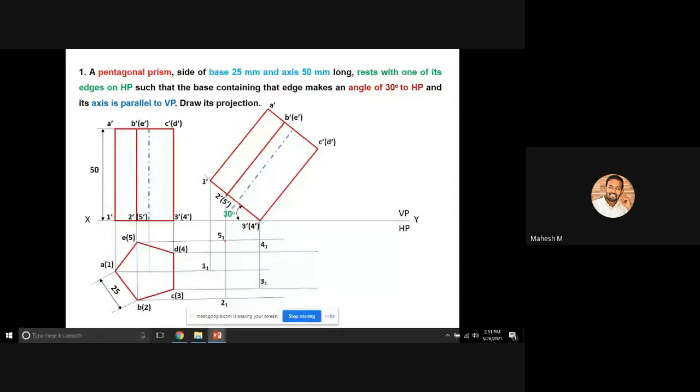Now you can connect these 5 points with the inclined lines. Connect points 1 and 2, 2 and 3, then 3 and 4, 4 and 5, finally 5 and 1. If you do this, you'll get an inclined pentagon. Okay, this is not sufficient for creating an inclined top view, so we have to project the remaining 5 points too.